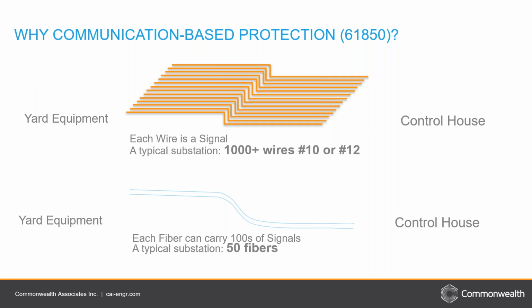And a fully enabled 61850 substation also led to a reduction of more than 1,982 hours of construction and installation work, compared to 3,508 hours of work that you would have to put in if the substation only had hardwired signals for protection and control and monitoring functions. So this shows that there's a significant reduction in material and construction cost that can be achieved while implementing 61850.